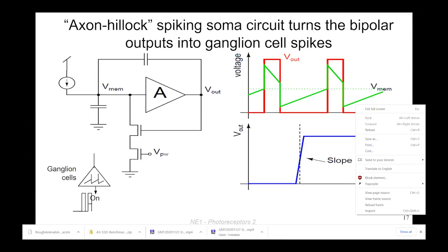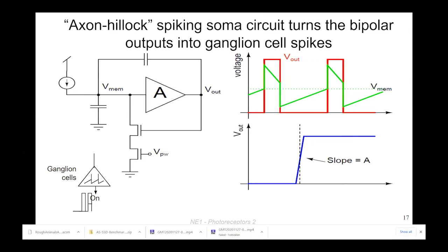Do you guys see the problem? If you use a traditional digital inverter that looks like this, then of course, as this voltage crosses half VDD, both of these paths are going to be on, and this thing is going to be burning many milliamps of current. That's a lot of power to burn just to slowly cross the threshold.